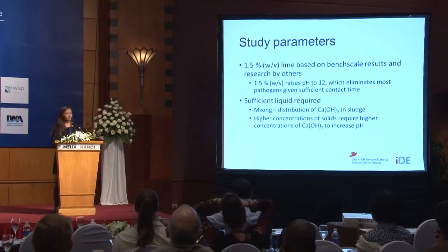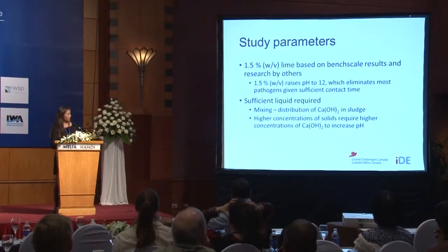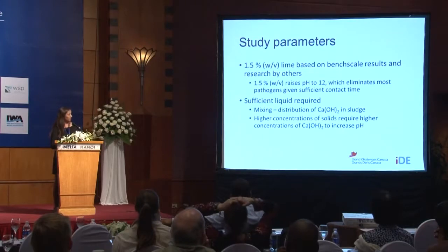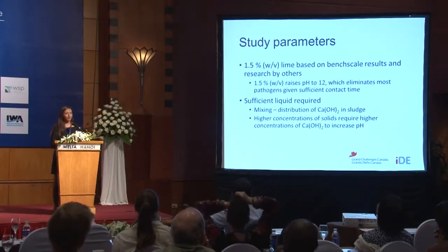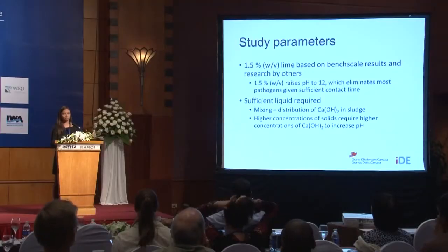Another important parameter is having enough liquid. This doesn't work well with a very solid sludge. You need enough water to make sure that the lime is distributed well throughout the sludge. And also, the higher the concentration of solids in your sludge, the more lime you need to neutralize those solids.